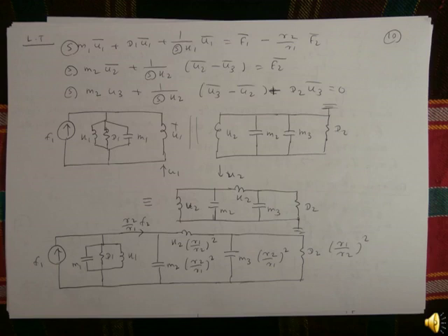Those are the frequency domain Laplace transform equations. The equivalent circuit diagram has F1, K1, D1, M1 on the primary side, and on the secondary side U2, M2, K2, M3 and D2. The primary and secondary sides are combined: the secondary side elements are referred to the primary side by multiplying by the turns ratio squared. The whole equivalent electrical diagram is represented in the diagram.